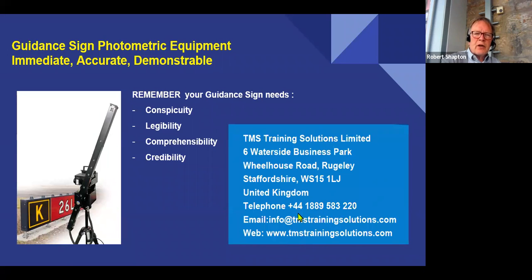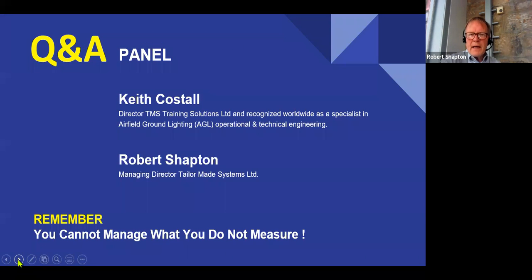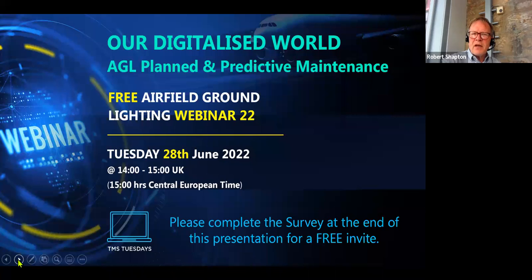There's no regulation that says you must do it at any particular interval, because it won't protect you if the sign is found to be a contributory factor in an accident and non-compliant. So the frequency of testing, as with all visual aids, will depend on the prevailing conditions at the airport. You do what is necessary to maintain compliance.